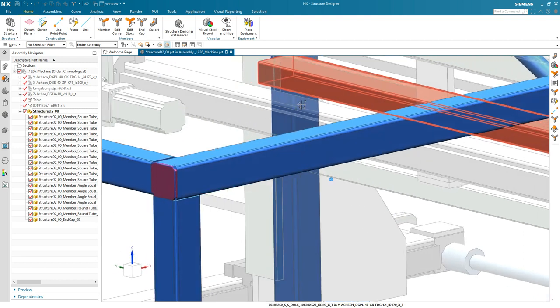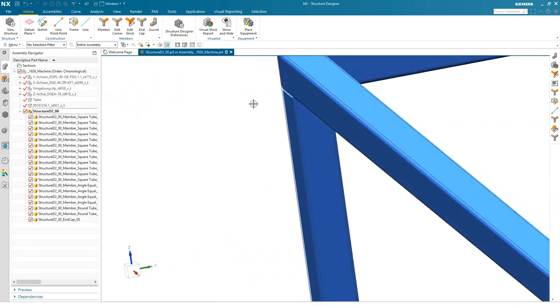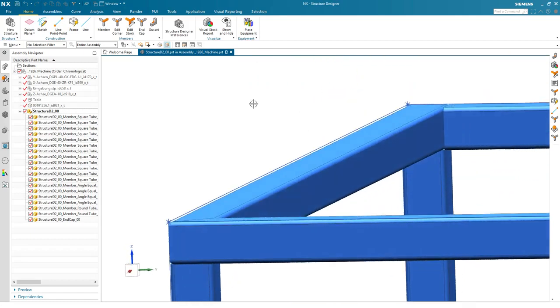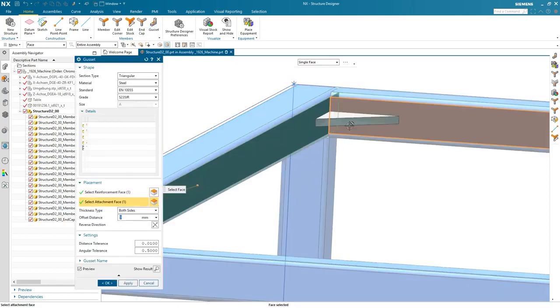And we have our end cap, and notice how it trimmed the faces off there. All right, now if you want to stiffen some things up, we have a gusset command that does that, kind of like a corner stiffener. All you need to do is simply pick the faces, and the system does the rest. Now we have options for triangular with a nose, square, rectangular, and you can even control the parameters or the sizes of everything with this table of dimensions.